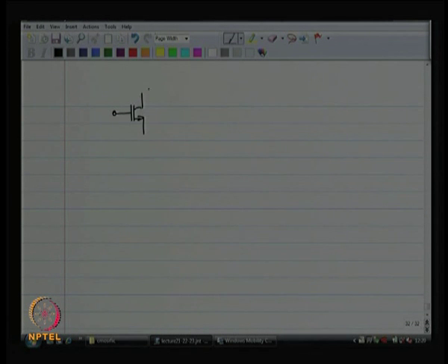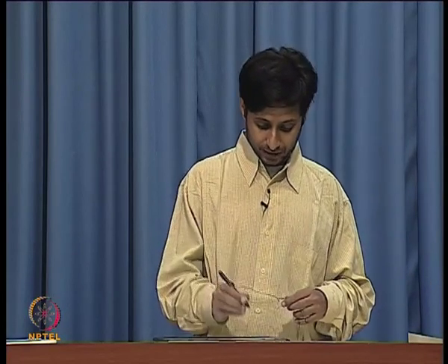So, the MOSFET model has a couple of things. Besides the capacitors, the MOSFET model has a gate resistance. It also has a channel inductance. Okay. So, you could use this particular property of the MOSFET model to your advantage and try to develop a matching network on the input side.